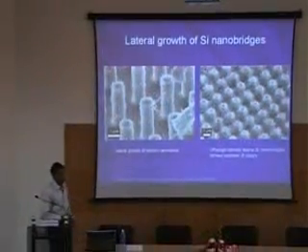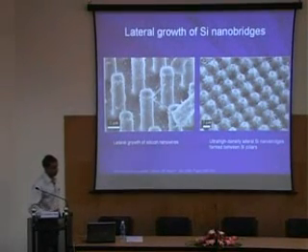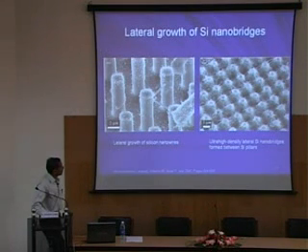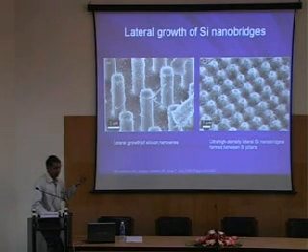Are you able to control in some way the number of horizontal wires that you have? Well, the number of horizontal wires depends on the presence of the catalyst on that surface. How well you can control putting these catalysts here will decide the growth of these nanowires horizontally. So you can envision patterns? Yes. You can have quantum-size patterns of these gold catalysts deposited on the side walls, from where the nanowires will grow.